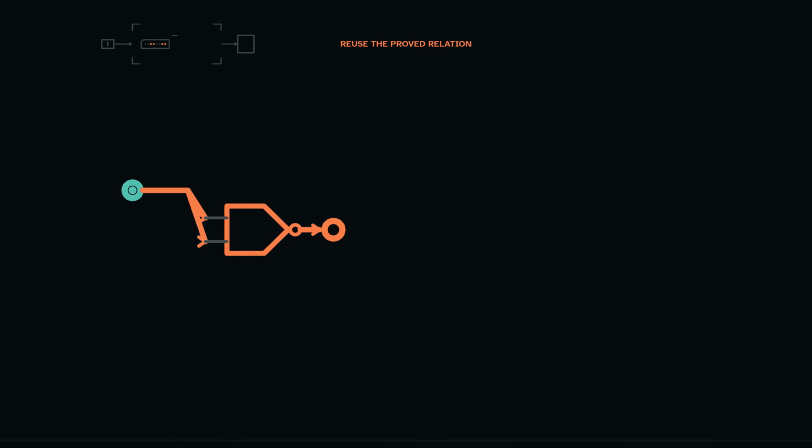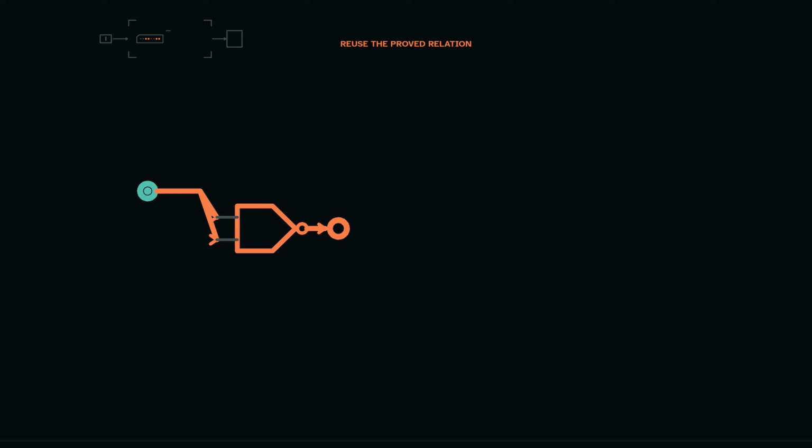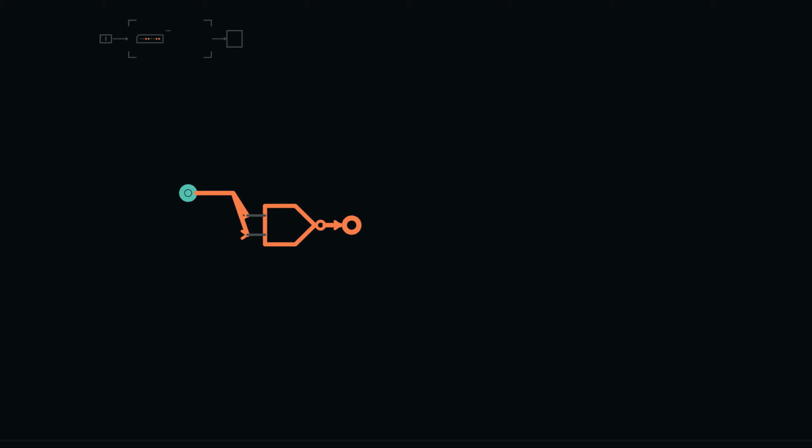Begin with NOT. One input route forks into both entrances of a NAND. If the input is 0, NAND sees 0, 0 and outputs 1. If the input is 1, NAND sees 1, 1 and outputs 0. There are only 2 possible input rows and both are now visible. The new outline may be labeled NOT because its output is always the opposite Boolean value. The fork copied a value to 2 inputs. It did not divide or weaken the abstract bit.